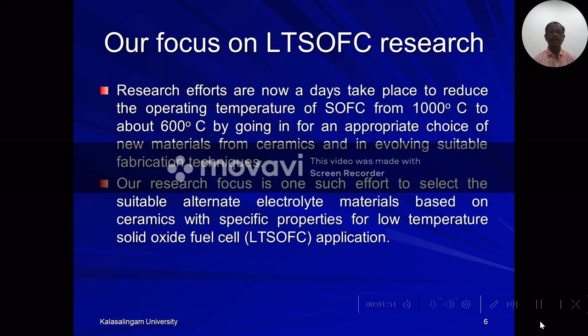Our focus is on LTSOFC research. Research efforts are nowadays taking place to reduce the operating temperature of SOFC from 1000 degrees centigrade to about 600 degrees centigrade by going in for an appropriate choice of new materials from ceramics and in evolving suitable fabrication techniques. Our research focus is one such effort to select suitable alternate electrolyte materials based on ceramics with specific properties for low temperature solid oxide fuel cell application.